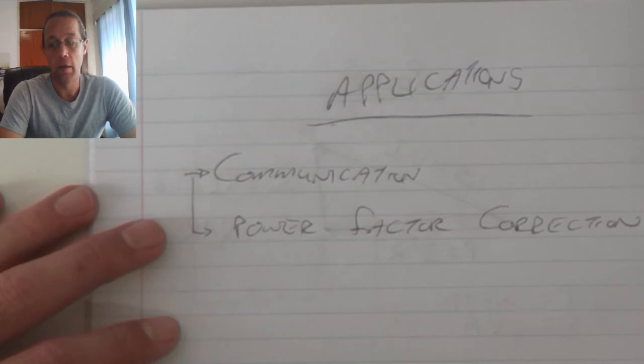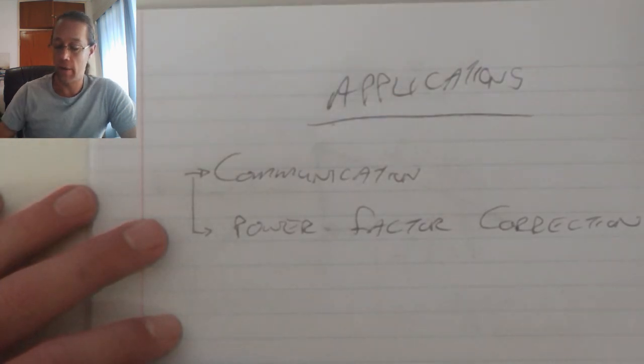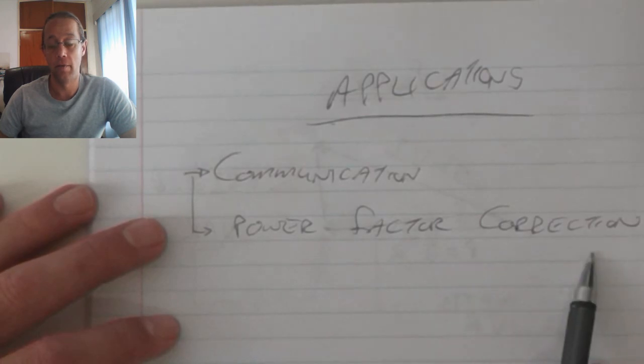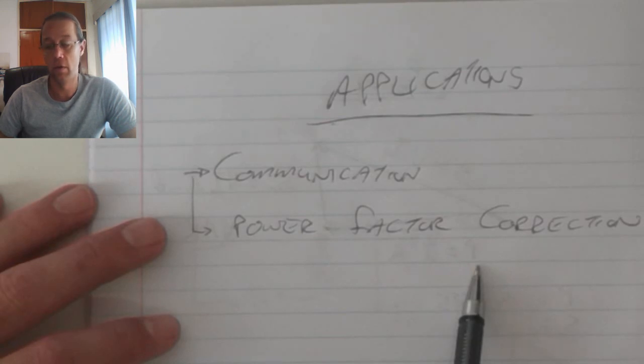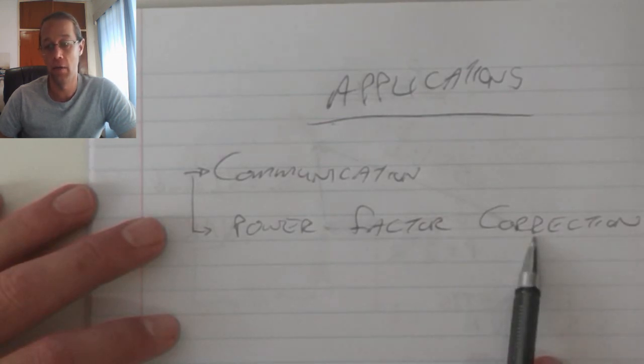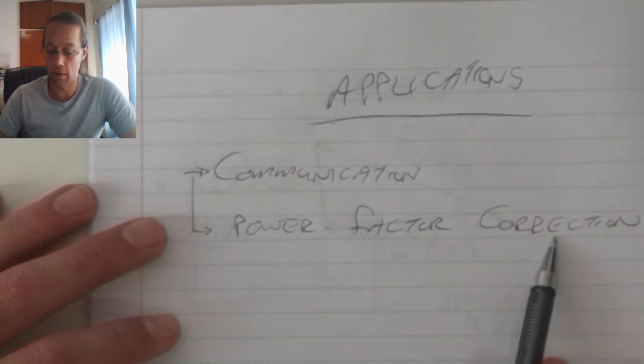So if we have a circuit whereby the inductor and the capacitor, or the inductance and the capacitance in the circuit are in harmony, thereby we will find a situation where the inductor and the capacitor is supplying current to the internal circuit, and therefore we're not drawing current from the supply, or we're drawing a lot less current from the supply.